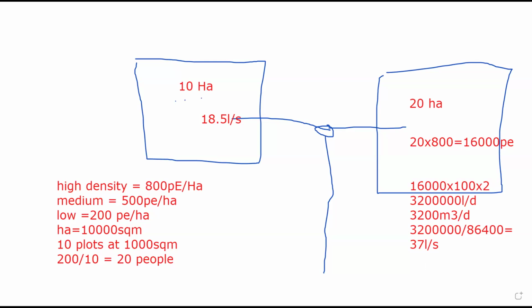You now go to your nomogram. And then let's assume that the slope here is 0.5%. That means I have measured between the point of the source and the last point here, and it's giving me a loss of 0.5 meters, 50 cm for every 100 meters, which is fair. You remember that? Those who attended last week.